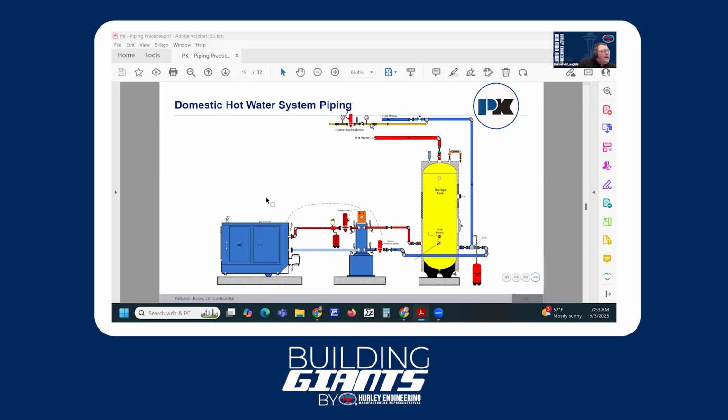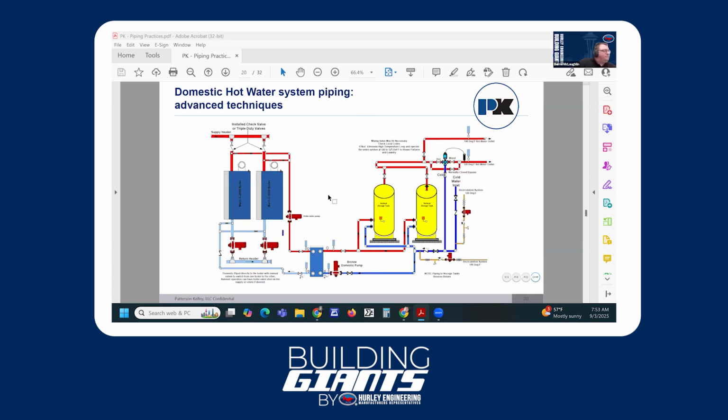But if this were a non-condensing boiler, then we have to be really guarded about what we do inside this heat exchanger. Because if we send too cool return temps, again, we risk damaging the equipment. So a lot of times when we get to this type of application, we might go to a shell and tube because we can control the delta T on it and control the return temp going back to the boiler.